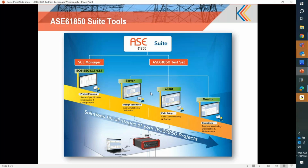A quick overview here. In our previous demo, we talked about the 61850 suite, but for those of you joining us for the first time, I'll explain. At ASE, we presently offer the ASE61850 suite solution. This solution covers all the stages of the 61850 project: the initial planning and engineering of device configuration, design validation through simulation of IEDs with our tools, field commissioning and testing capability, along with the ability to passively monitor and assess 61850 communications between devices.